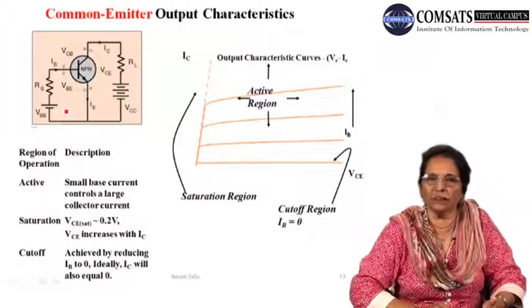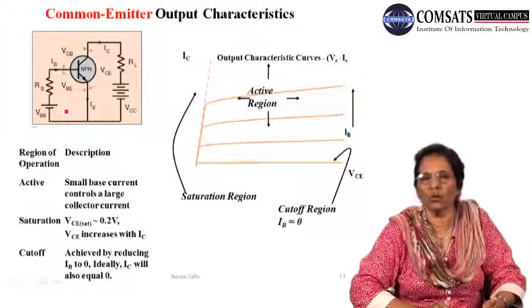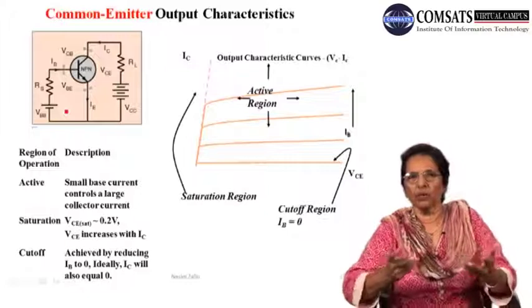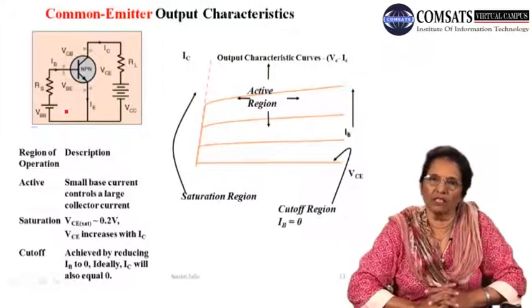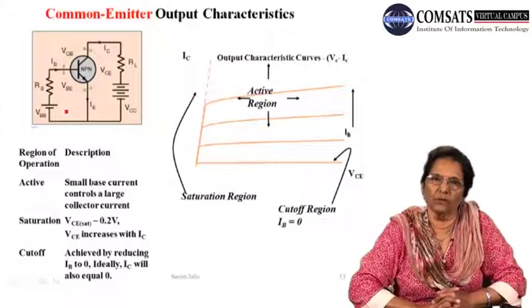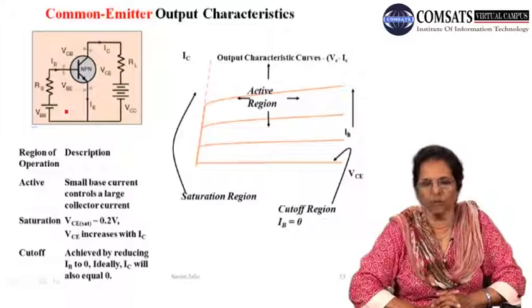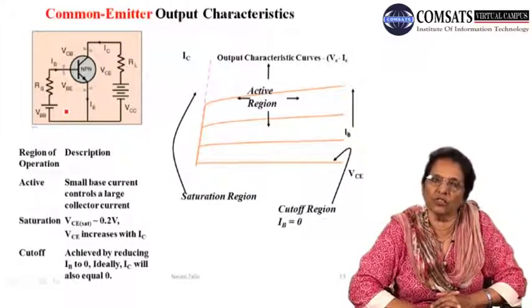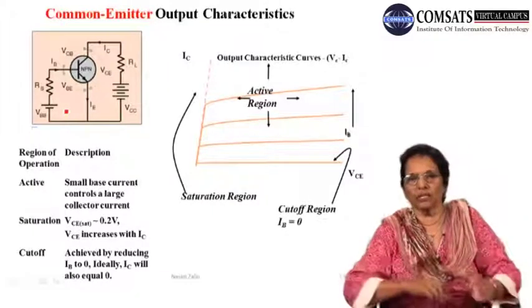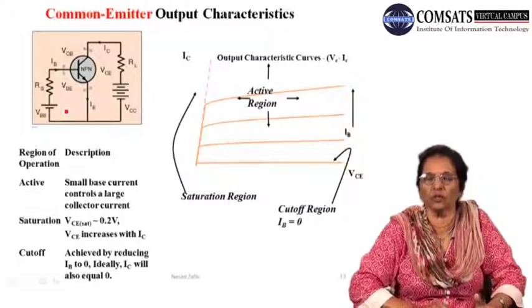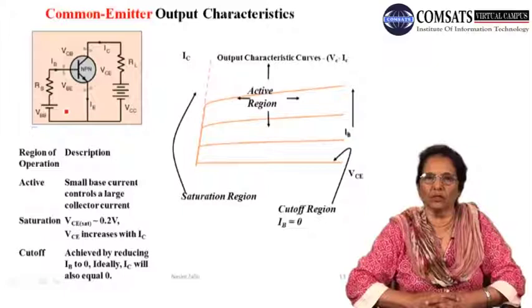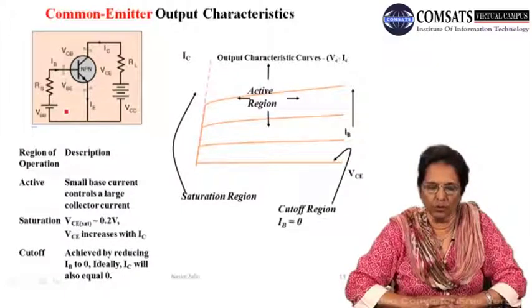And again, as I mentioned in my previous lecture, we include two resistances, one a small resistance, to avoid a breakdown, because we do not want to pass a large current through the base, and also the load resistance RL, so that you can obtain the voltage out. You can see the output voltage on the oscilloscope and measure it across the load.